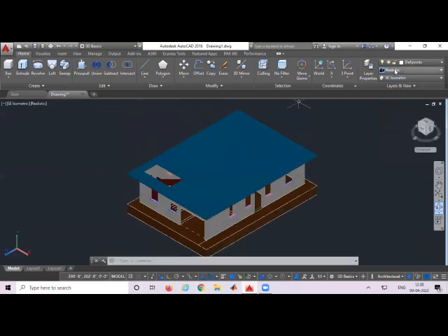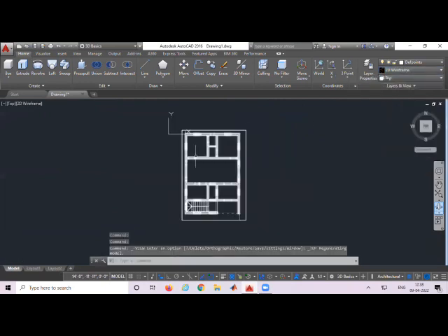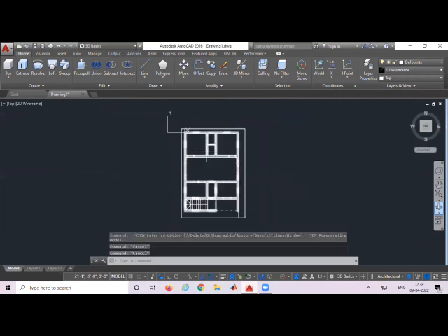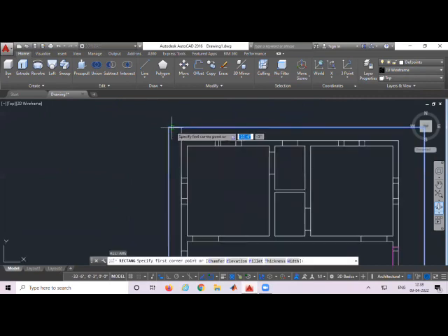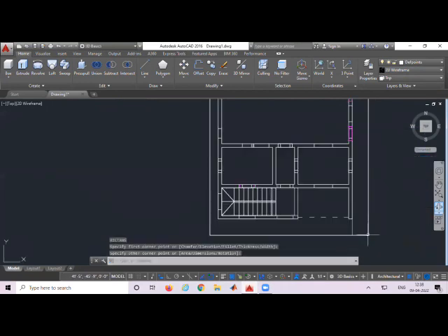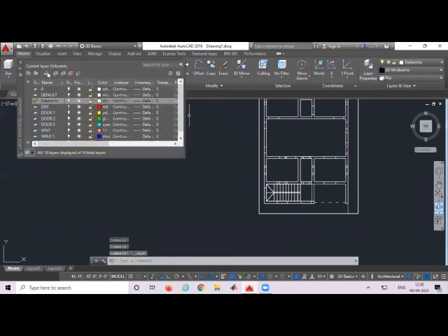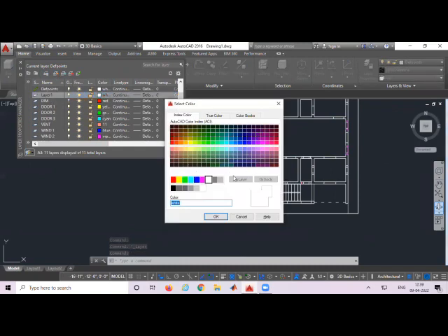So you can glance over this structure, how it is being converted into different colors with different kinds of materials. Now I just wanted to change it into the 2D wireframe with the top view, so that I am able to create a rectangle. By creating that rectangle, I wanted to create a railing around the top floor of the slab, so that we can create a parapet. Instead of the parapet wall, I wanted to create a railing with proper balusters.